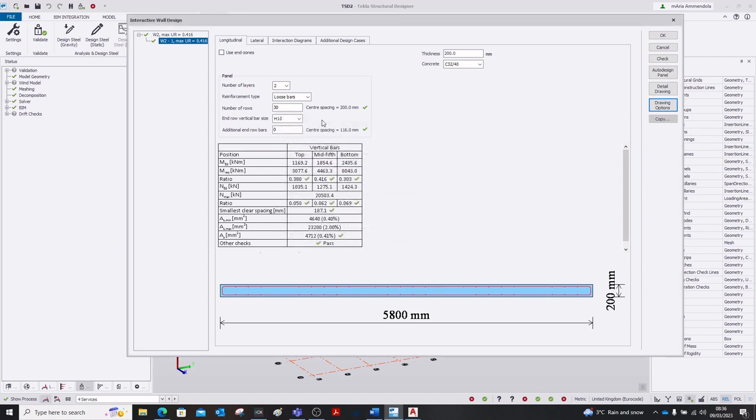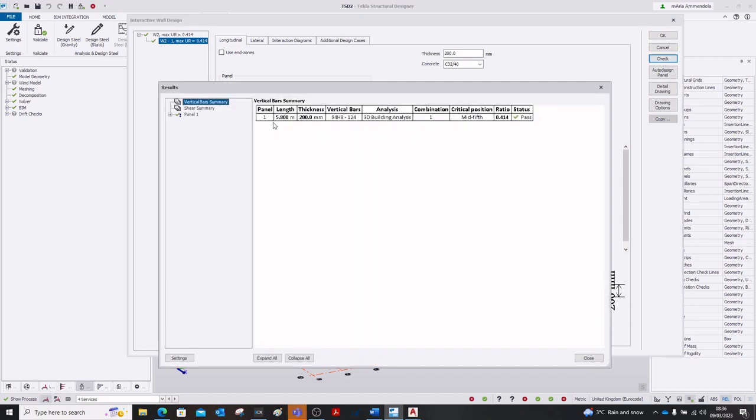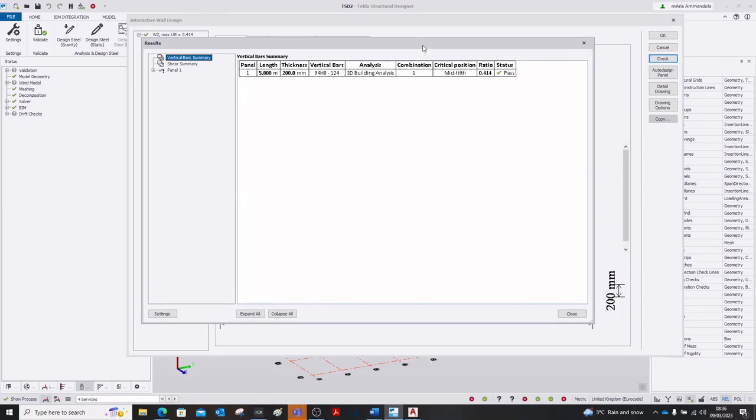And also, in case, let's imagine you set something that is not working, you can push the Auto Design panel. It automatically is gonna set again the design and set again the minimum bars you need basically to have everything verified.